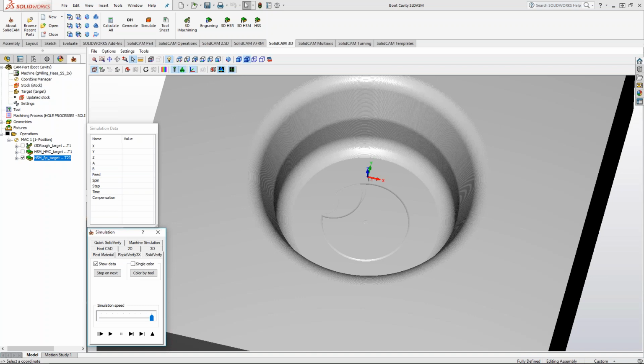If you run coolant on these carbides, they could go into thermal cracking, which means when you're in the cut, the tool heats up. When you come out, the coolant splashes on it, cools it off, and then it goes back in the cut, and it's an endless cycle. So heat, cool, and whenever you start doing that, it starts stressing the tool, the coating, and you start getting thermal cracking, and that starts breaking down the coating, which in turn starts breaking down the tool.